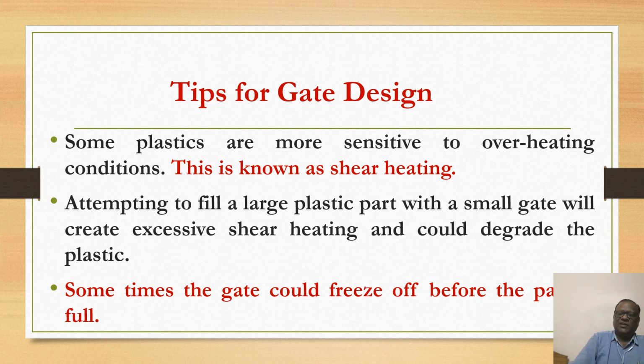But suppose the cavity is not filled and the gate is frozen, then there will be a situation of short. That means you won't get an entire component. Out of your 100% of that component, only some 60%, 70% might have filled, and the remaining 30, 40% is left empty. So again the product will be rejected.